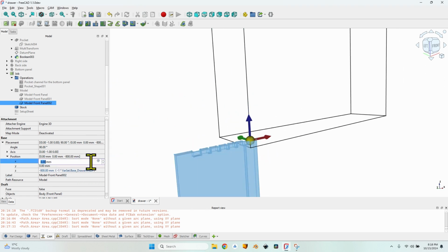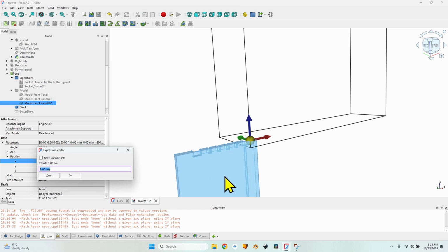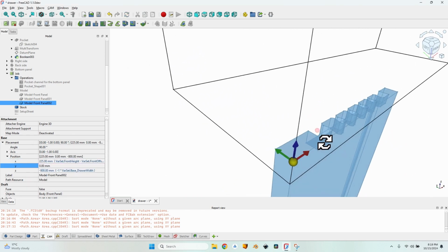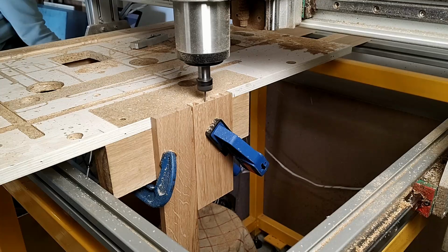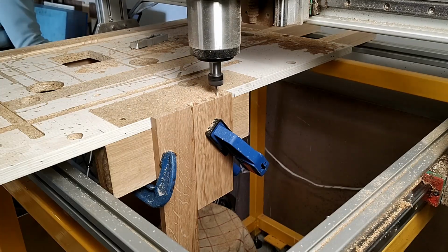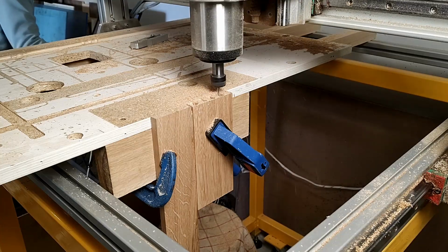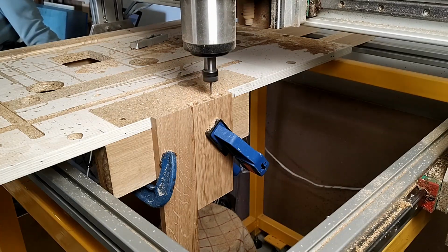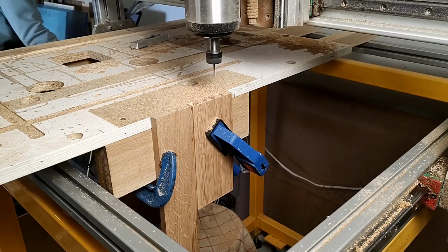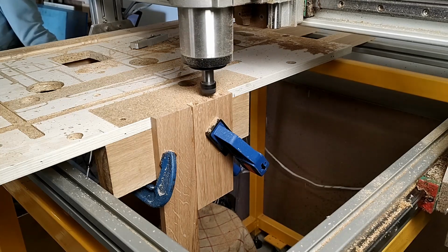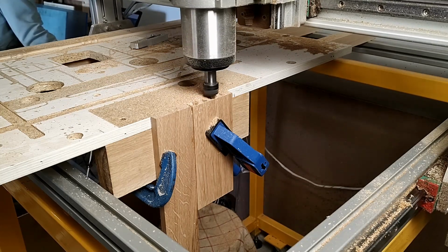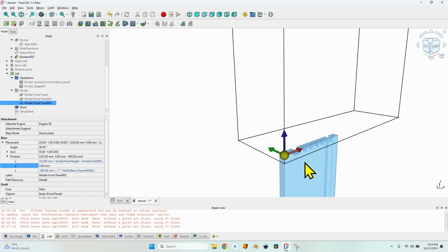Now let's move it on the x-axis, click on the expression, and I will move it to the right with the front height minus again the front offset. And now it will also start from 0, 0, 0 downwards, just as I set everything up. When I'm milling end of boards, when I place objects vertically, I like to start from Z and go down with a minus value. When I mill faces of objects, when they are sitting flat on the table, I like to take the Z0 of the table and place the object above that value.